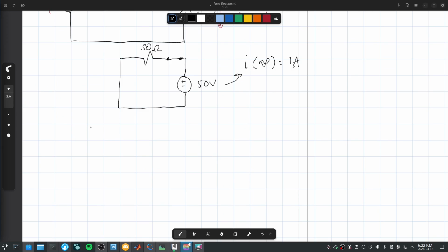So, with inductors, the rule is that, say a current is this amount, so this is current over time, it's going to stay at some amount, and then once the change happens, it's either going to drop down to the second level, or it's going to increase to some other level. So, we can find our initial I by looking from the left side.